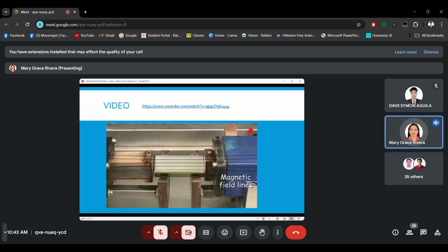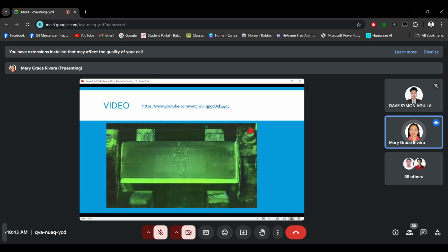Our test sample has been magnetized in horizontal direction. The magnetic field lines run horizontally. This is the reason why cracks in vertical direction are visible particularly well. To make sure to detect all near-surface cracks, one has to magnetize the sample once more and best perpendicularly to the first time.